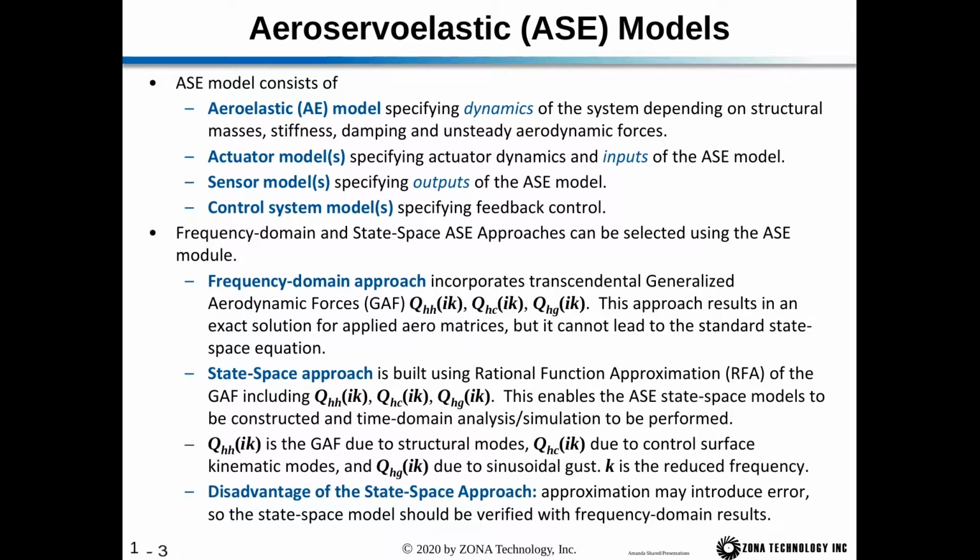The aero-servoelastic models in ZAERO are described here on this slide. The ASE model consists of the aero-elastic model, which specifies the dynamics of the system depending on the structural masses, stiffness, damping, and unsteady aerodynamic forces. Then you add on top of that the actuator models, which specify the actuator dynamics and inputs of the ASE model. You also can specify sensor models, which specify the outputs of the ASE model. And then finally, you can optionally specify control system models for feedback control.